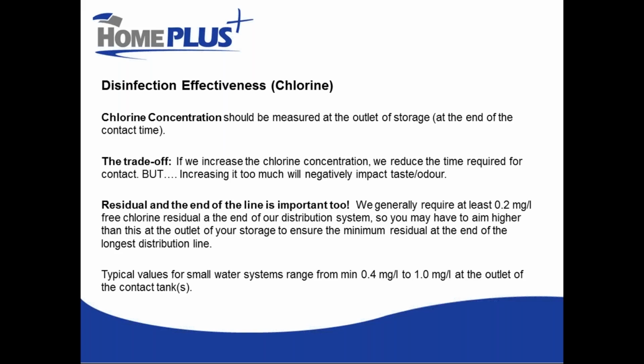So sometimes we'll have to aim quite a bit higher than what we normally would want to do at the end of our contact vessels or storage in order to get that residual as high as we need it at the end of the distribution. The more extensive your distribution is, the more challenging that becomes. And of course, the trade-off is that if we increase the chlorine concentration too much, we will negatively impact taste and odor.